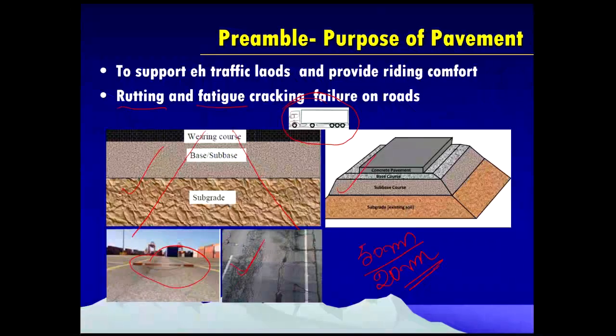You can ask me, sir, what is the problem with doing that with natural materials? That's fine. But as I told you on the very first day in my lecture on low volume roads, the whole world is already facing a crunch of natural materials. If you use geosynthetic materials, there is every chance that we can reduce the consumption of these materials. We can reduce the thickness of the layers, thereby saving materials.